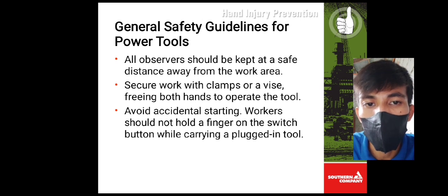All observers should be kept at a safe distance away from the work area. Secure work with clamps or a vise, freeing both hands to operate the tools. Avoid accidental starting. Workers should not hold a finger on the switch button while carrying a plug-in tool.